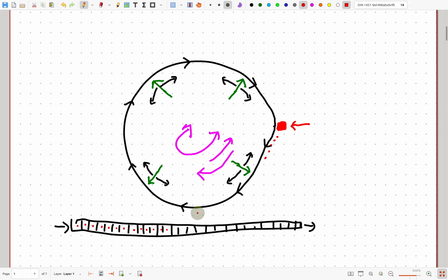And if we're moving the buffer at a speed which doesn't line up with our sample rate because we've sped it up or slowed it down, that then gets a bit awkward because our samples may no longer lie on our tape. We might have multiple samples within some cells and some cells without any samples, and so on and so forth. So it turns out that the easier thing to do digitally is to keep the tape running at the same speed but change its length.